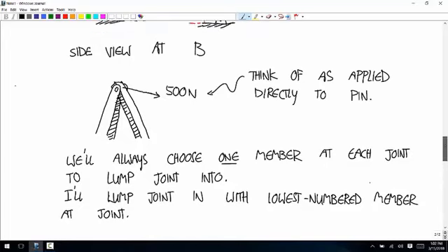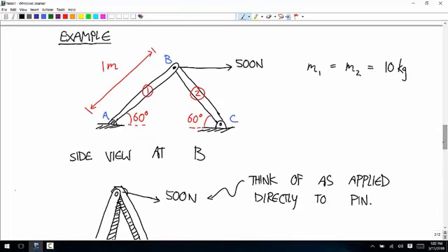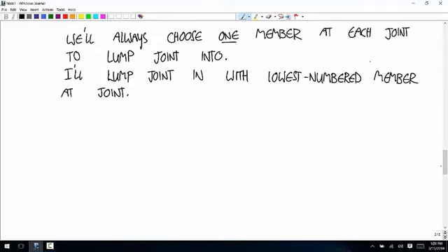Okay, well, if we're going to calculate the external forces on these members, we're going to have to isolate those individual members. So I'm just going to go through one by one. I'm going to first use Newton's laws for member 1. Then I'm going to use Newton's laws for member 2. We're going to have a bunch of variables, a system of equations, and as soon as you have as many equations as you have variables, you can solve it. So first, member 1.